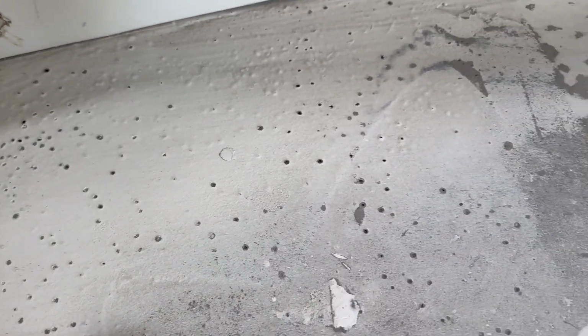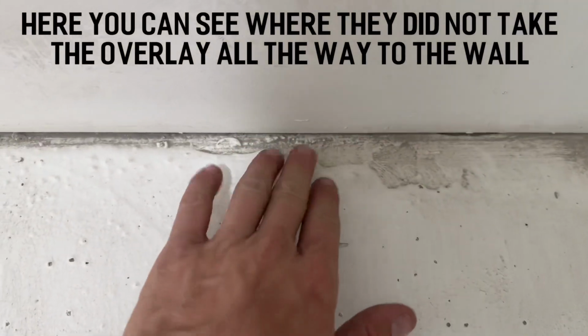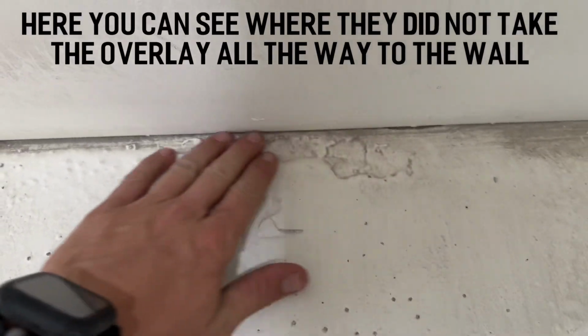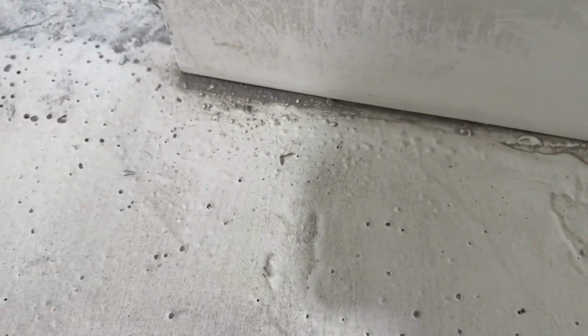To prevent any coating defects, properly clean the concrete surface before coating application. Monitor environmental conditions such as temperature and airflow during the coating application to prevent outgassing and defects. Addressing concrete outgassing is crucial for achieving durable and effective coatings on concrete surfaces.